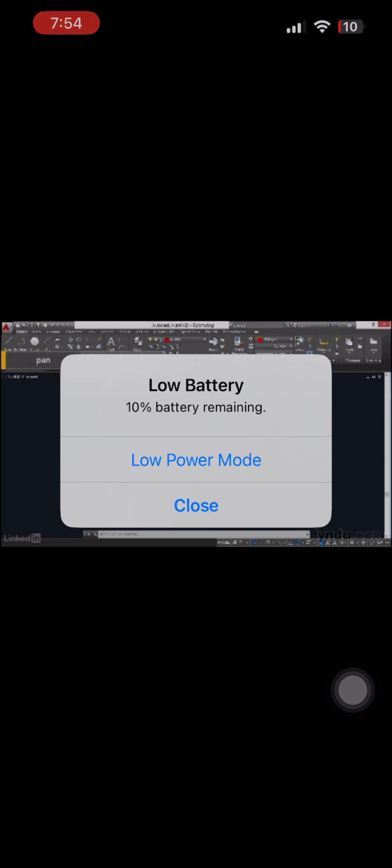Now, let's talk about the mirror command. It also creates new objects based on the existing objects in your drawing. Its icon is located right here. Click Mirror. It says Select Objects. I'd like to mirror everything in the room with the exception of these two lines. So I'll hold down Shift and click these two lines to remove them from the selection set.